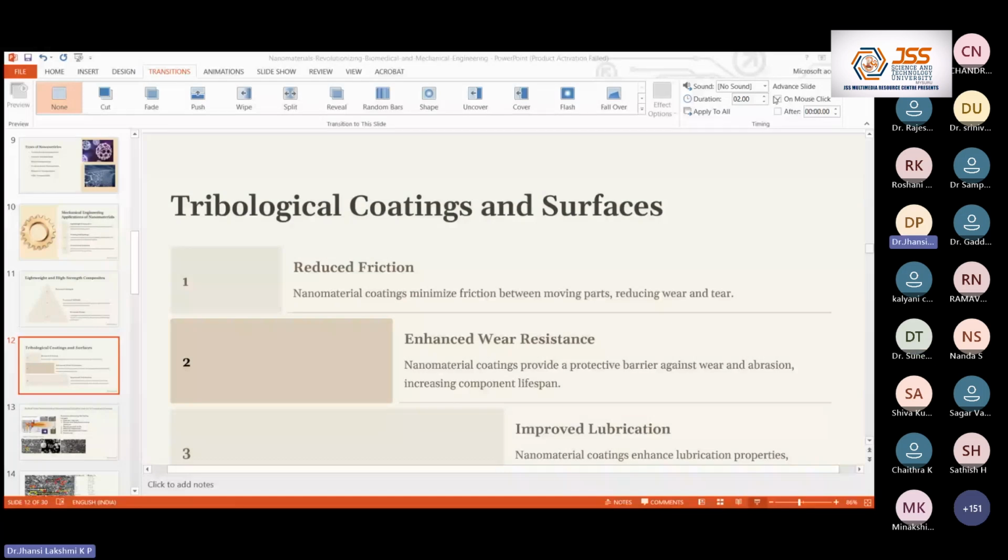So we have chosen the substrate material, which is used in high temperature applications, and also the coating material. Now how to coat this coating material on this substrate? To coat these hard materials, we generally prefer thermal spray coating methods. What are thermal spray coating methods? In thermal spray coating techniques, the material is heated and accelerated onto the substrate. Here we are using the plasma spray process.